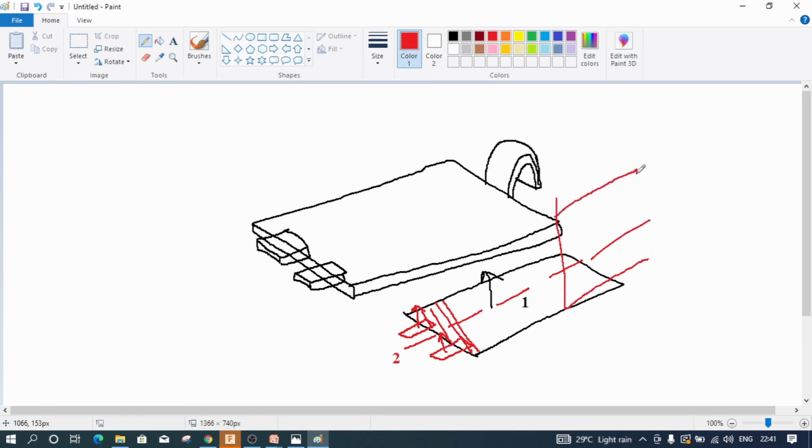On this plane, we need to draw something like a U-shaped object. This is going to be the path of the profile. After this is done, we draw a rectangle here. If you draw a rectangle and use the sweep command, you will be able to develop this particular feature like this.